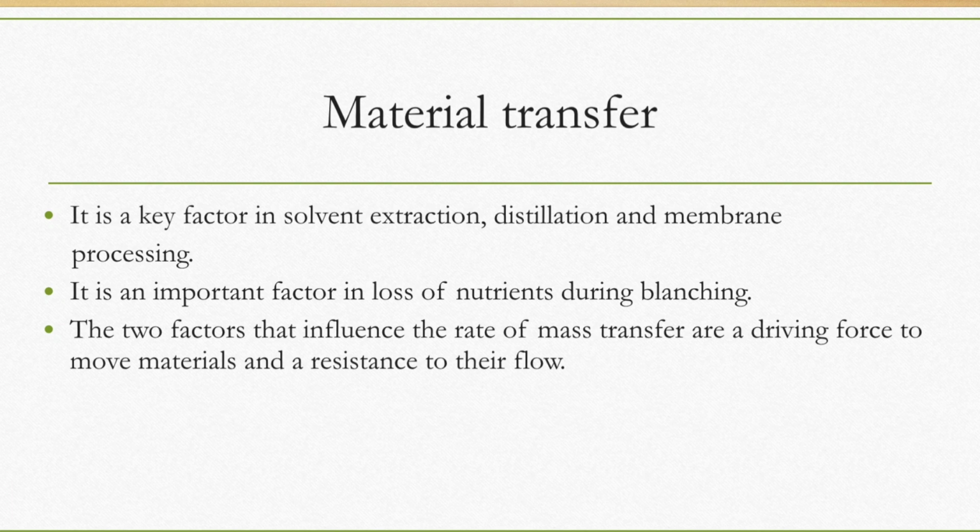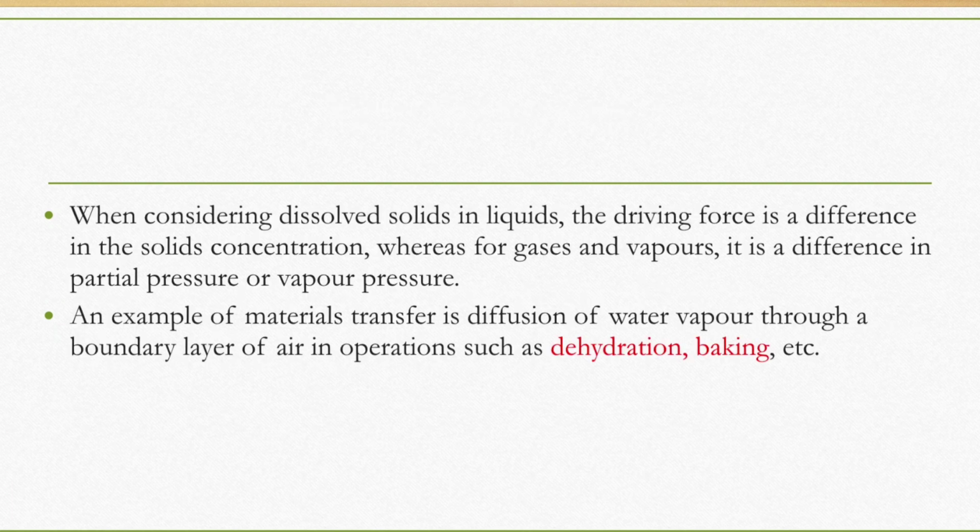Now, there are two factors that influence the rate of mass transfer. One is the driving force, which is used to move the materials, and the other is a resistance to their flow. When considering dissolved solids and liquids, the driving force is the difference in the solids' concentration, whereas for gases and vapors, it is usually the difference in the partial pressure or vapor pressure. So this is one such example.